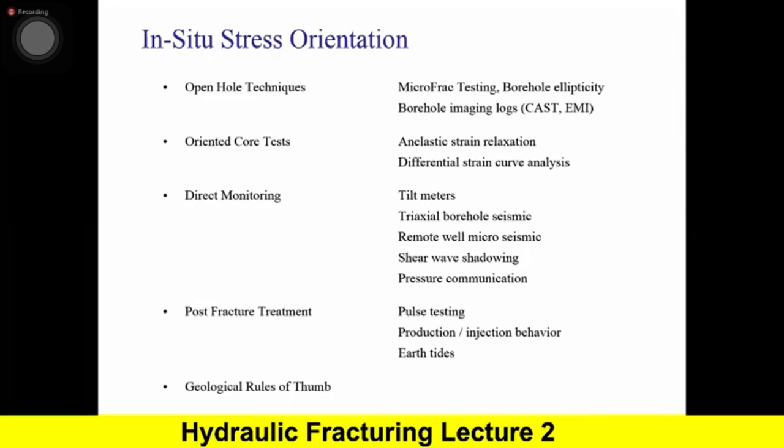In situ stress orientation is very important. There are multiple techniques to calculate it. Let us wait till we talk about testing next week. There are a lot of ways to do it. Next week we'll talk about microfrac testing. I may add something about elastic strain relaxation.